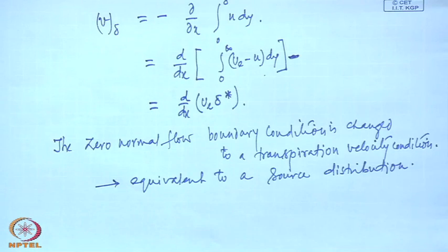As we mentioned earlier, in an interacting situation where one affects the other, which is of course the natural case, the inviscid flow affects the viscous flow and the viscous flow in turn affects the inviscid flow. Either of these two approaches is to be used for interaction.